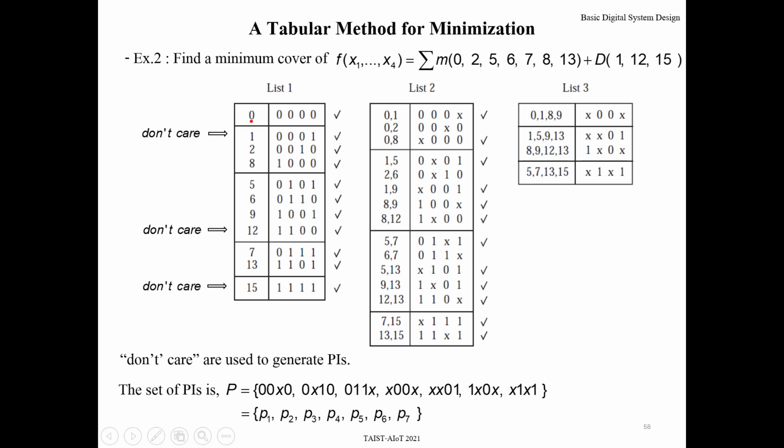After that, you compare to combine, or find one bit different values from elements in the same group. Namely, for example, this one differs by one bit. So you take this one that is already combined together and it becomes 00x. 0 and 2 differ by one bit here, so it becomes this. 0 and 8 differ by one bit at x1, so x1 is x.